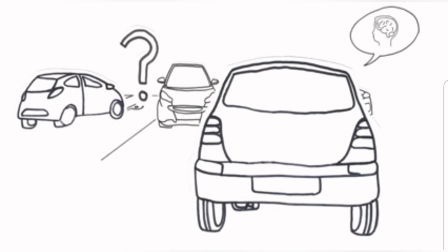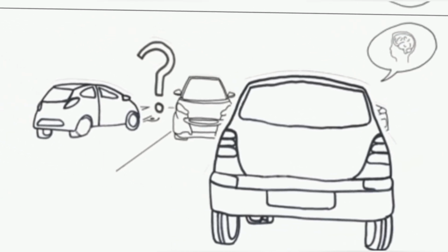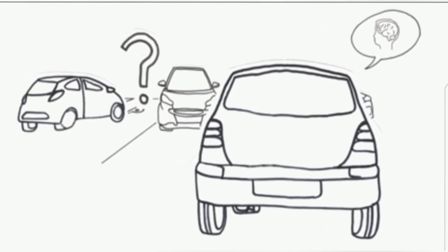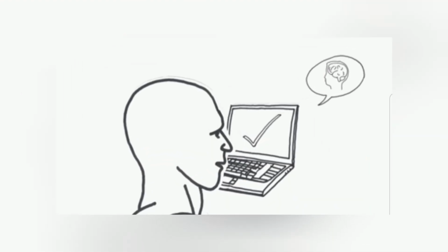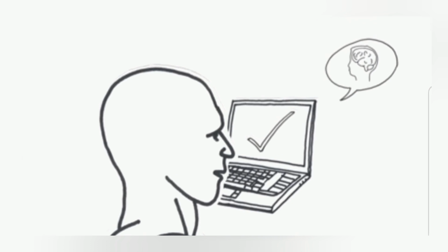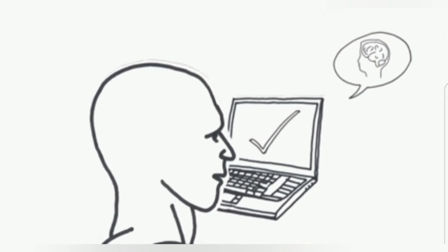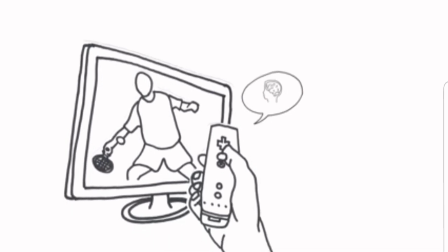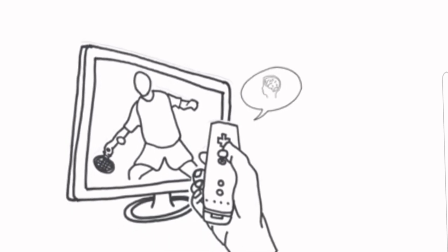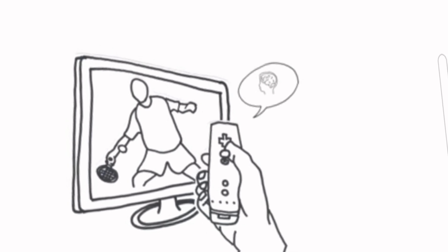Let's review what we have covered today. Sensors are a part of everyday life at home and work. A sensor is a device that can see, feel, hear, smell, and even taste. In process control, sensors are classified as passive, requiring an external excitation to produce an electrical output, or active, producing a voltage output without any external excitation.